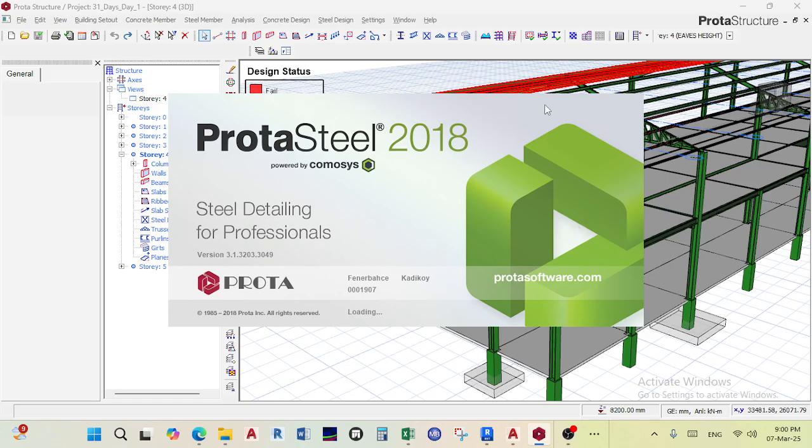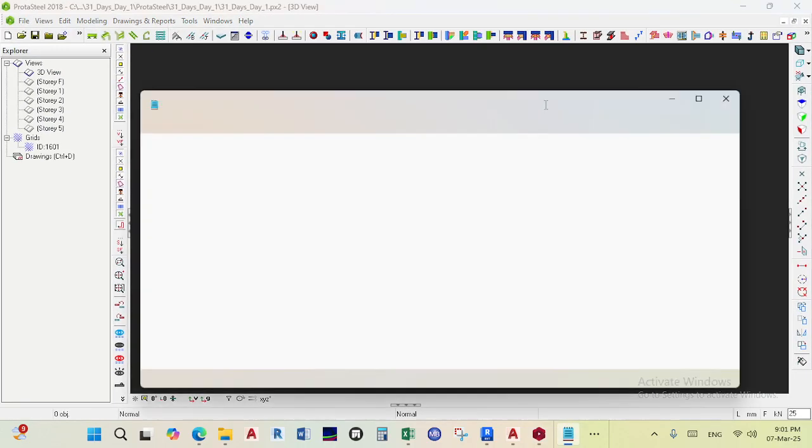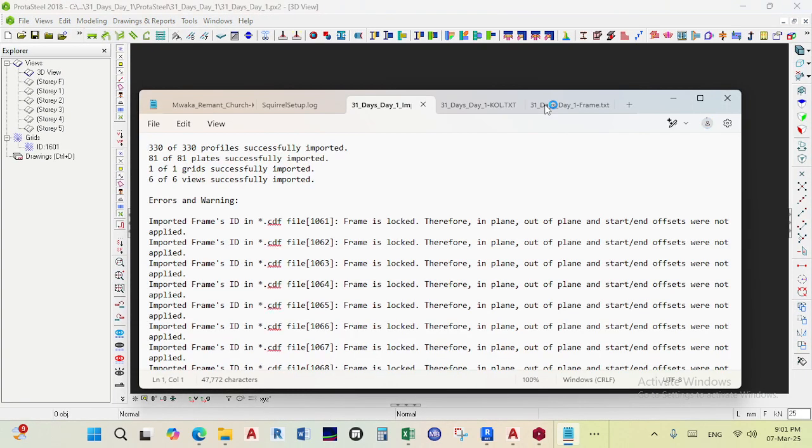Most of the connections, unlike Revit, you have to put them manually. But if you've got maybe 2020 or 2022, there's a thing called interactive combination, I think, where when you select the whole structure and right click, it will choose the best connection details for you. It's very fast and far much easier. But for this one, we'll just have to do it manually.